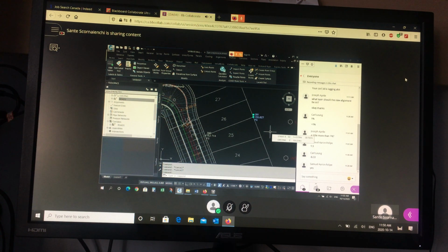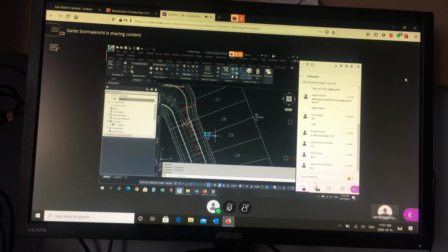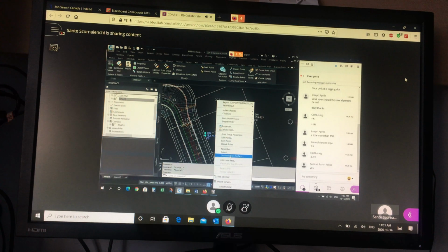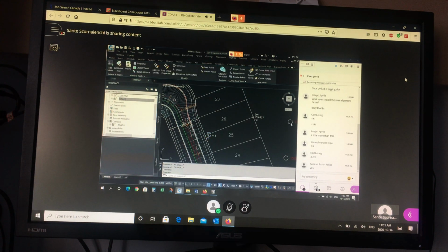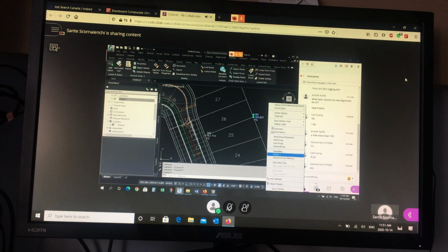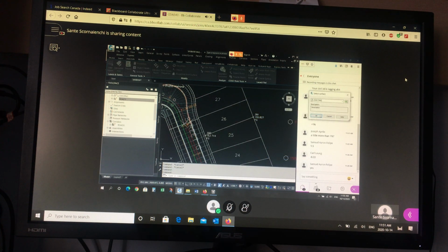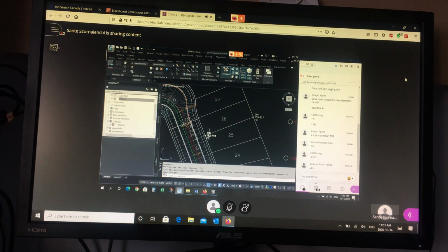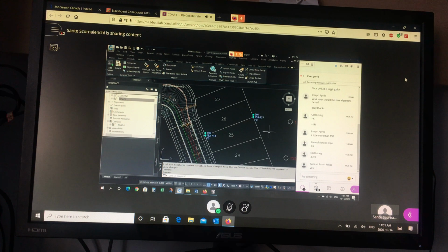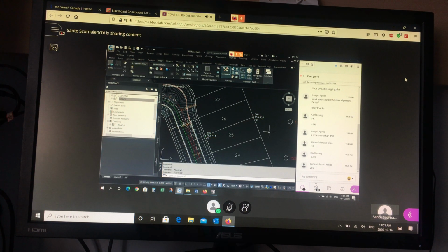So you need the first assignment surface to be correct to get this elevation, and you need the third assignment corridor model surface to be correct to get the front lot corner. Right? So this elevation comes from the road surface, and this elevation, same function, comes from the existing ground surface. And now I have an elevation at the front, an elevation at the back. I'll teach you what to do in between after the break.